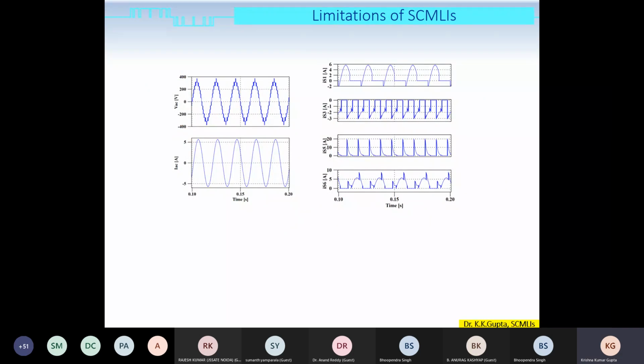For the structure that I was discussing, here I have shown the waveforms of currents also. This is a 13 level output of the topology that I was showing. Here you see the current through the load is around 6 amperes. But for some of the switches, the current touches a value of 20 amperes also.